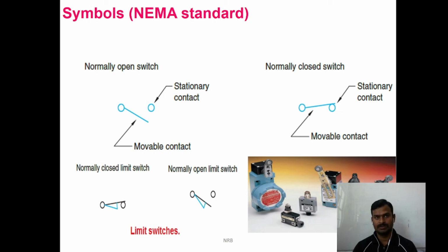In conveyor controls, of course, we have many stations, maybe like water filling applications and all those things. At each station we can use one limit switch so that the conveyor will be stopped at that particular point, and once the filling is finished, then with the help of another sensor, the conveyor can run again. So these switches are used to control many applications, as I told you earlier.